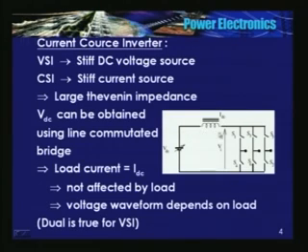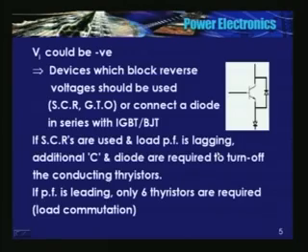We had connected a three-phase AC source, and a DC link inductor to filter out the current, and the load can be equivalent to the back EMF of a DC machine. Of course, the direction of current of these devices should be opposite. So almost the same operation we have here. At any given time, only two devices are conducting. One phase is open.